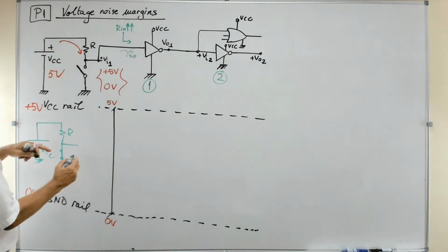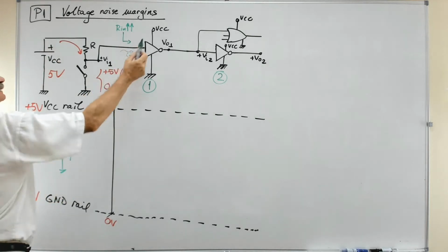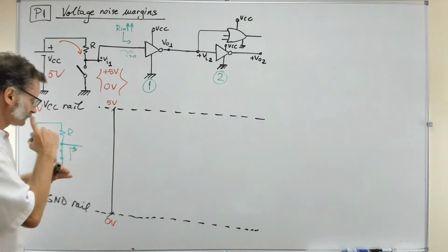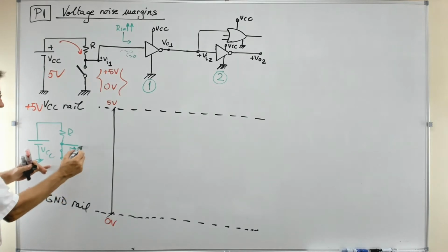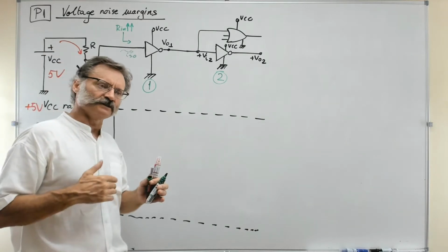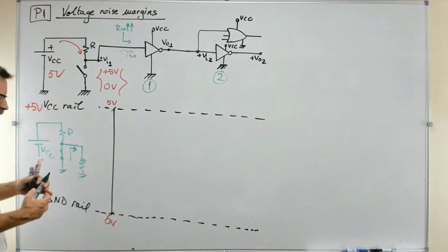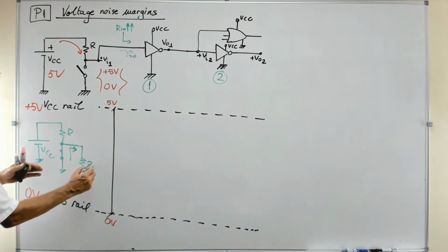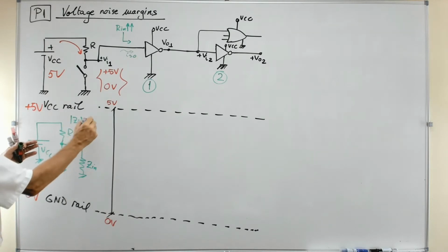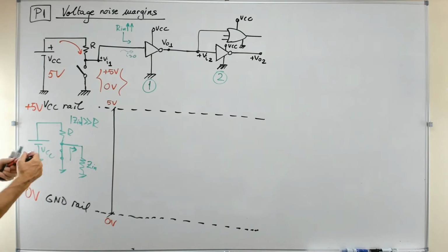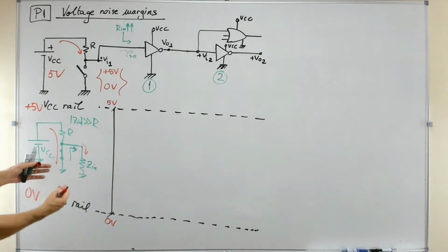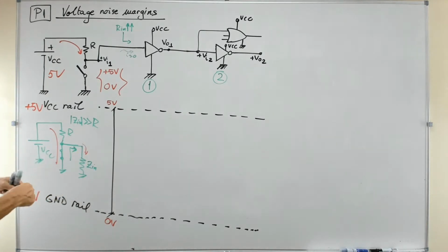And then here is the Thevenin equivalent of the input of the gate, because this is an electrical circuit. We will talk about this later on, but now you may imagine that it is an impedance. It may be capacitive and with some part of inductance as well, and some ohms of losses. So that is the Z in. So in some way or another, you may imagine that Z in is a huge value compared to R. So all the current goes through the circuit and very few current goes through the Z in. So it is as if it were superfluous in some way, to make it simpler.